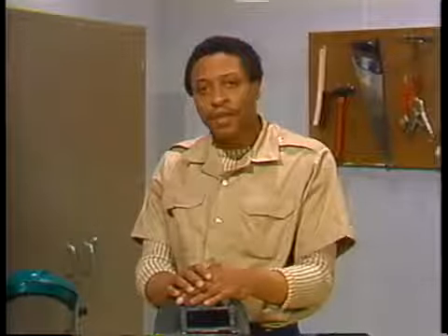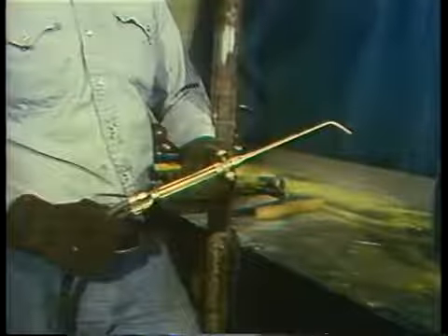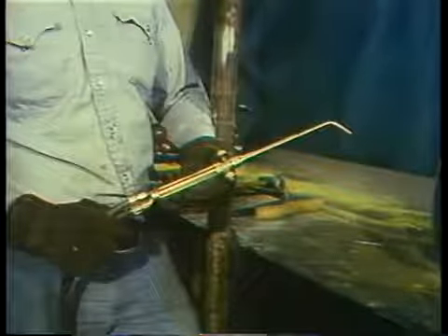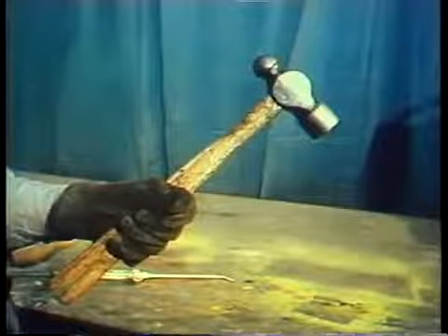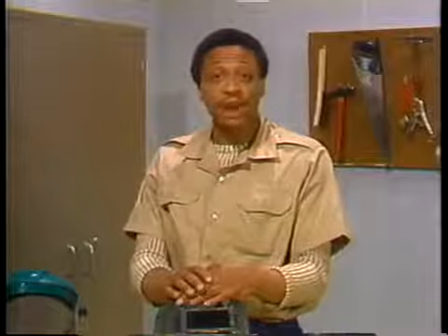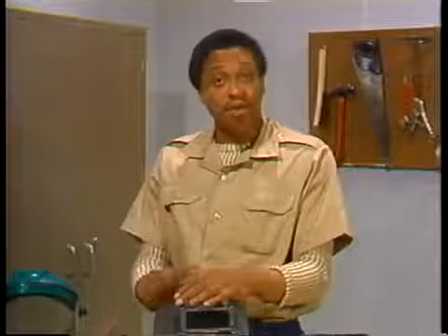The equipment and material that will be used is the same as the gear we saw earlier, except that now a gas torch and a hammer will also be used. The torch is used to heat the tube metal. This makes the rupture easier to close. There are several ways to close a rupture, and we'll demonstrate one method shortly.